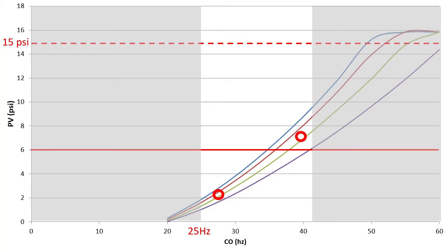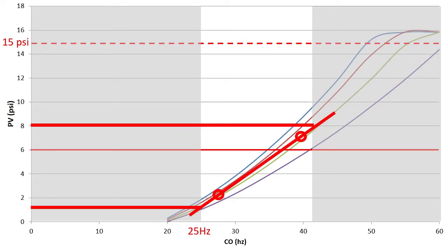You know your system, so you could probably come up with a pretty good guess on a couple data points you can use to extrapolate PV min and max over whatever you know your drive's min and max operating frequency should be. You'd be surprised at how tolerant PID is of that line you give it as long as you're in the ballpark. It won't give you optimal results, but you'll be amazed at how well it works.